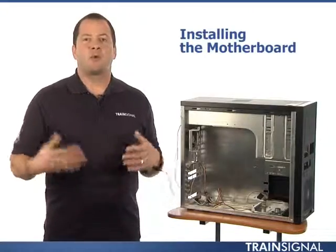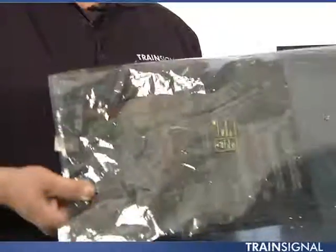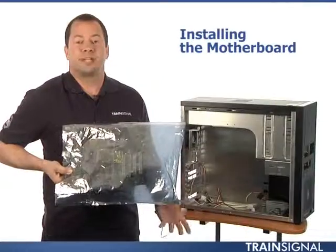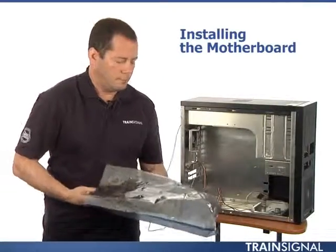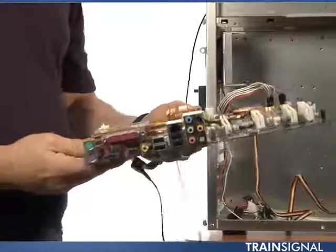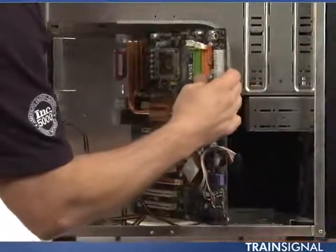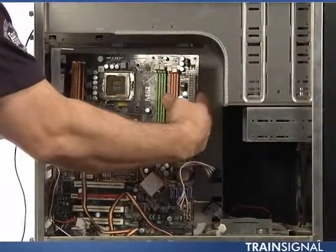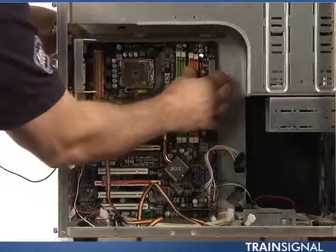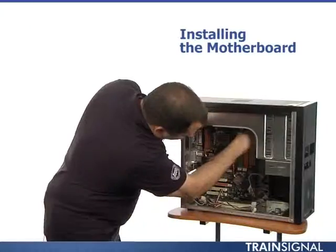So now that we're properly grounded, we're ready to proceed with the installation of the motherboard. You can see it's actually inside an electrostatic bag. This, again, offers additional protection against potential static discharge. We remove it from the bag, and then we're ready to proceed. It's important to align the holes at the rear of the case where the ports are. And next we will secure it so that it doesn't move.